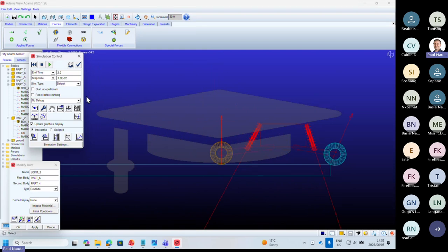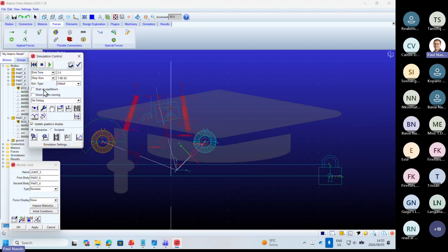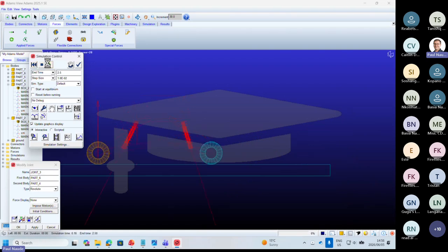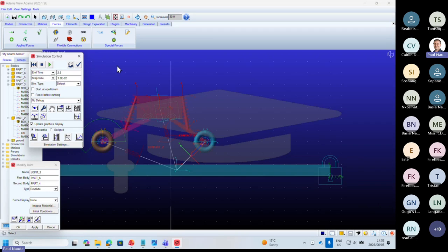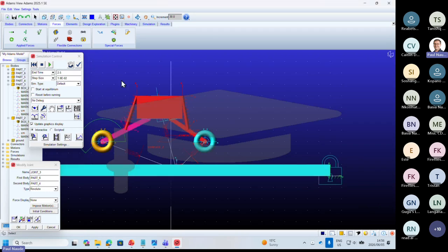Let's see what happens if I let it go for another half a second. Yep, there we go, across the side. What you'll also see is those arms go right through this body, again because we didn't specify contact, but it's not necessary. The contact we have specified is sufficient for our purposes.